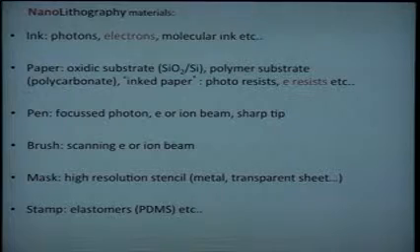And then paper could be, people still use cellulose paper for nano patterning. There are some results in the literature. But commonly supports like silicon dioxide on silicon with a given thickness. Typically SiO2 would be of the order of 100, 200, 300 nanometer, well-defined thickness of the SiO2, because in the device it serves as a dielectric barrier, okay? So its thickness is important. And then polymeric substrates and polycarbonate, for example. The CD, DVD material is polycarbonate, so you can see the fine grooves which are there around.